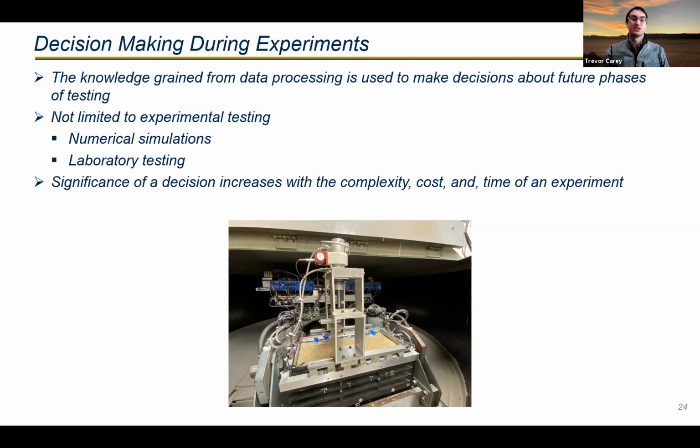While these are the same decisions, if you mess up a laboratory element simulation or element test, you may be out a day and a half. A numerical simulation, you can just hit reset. As you saw with that picture and that video of the foundation settling into the model, you can't redo that. Once that's happened, it's done. And that makes dynamic centrifuge testing a function of decision making, or a process of decision making.